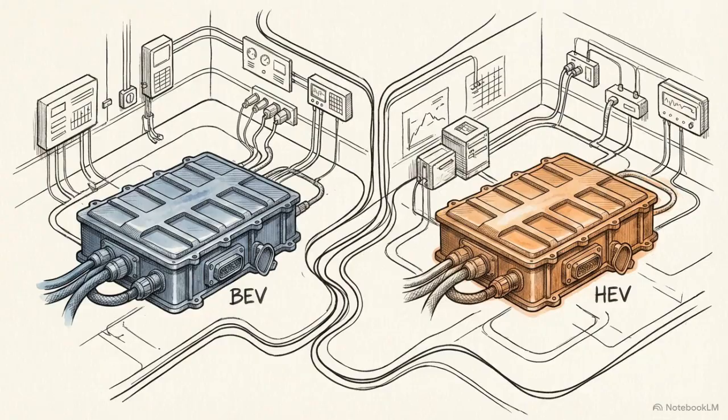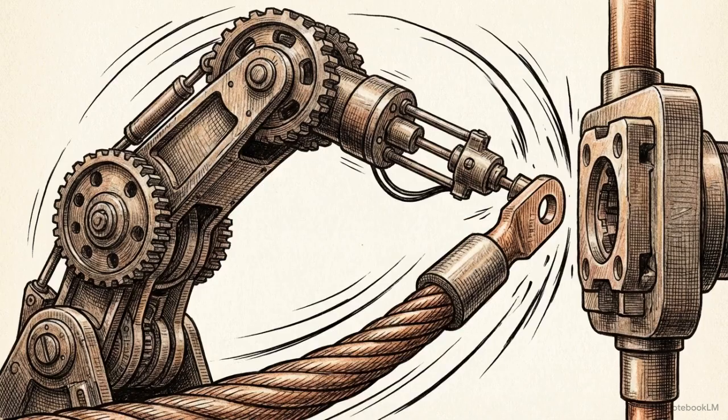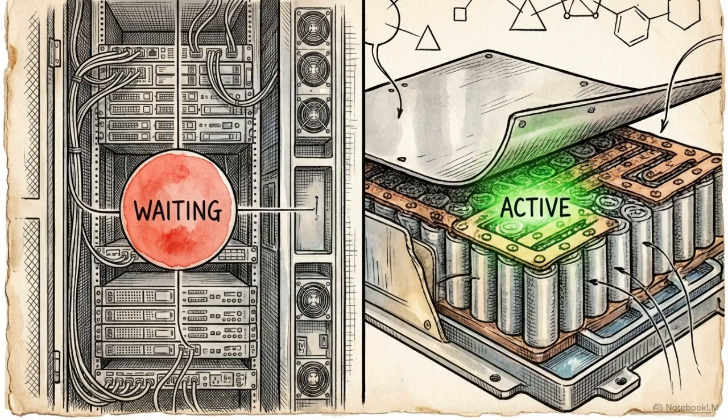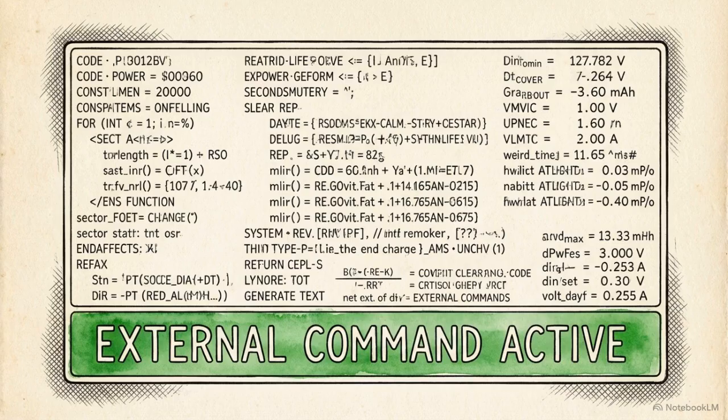This is a rigid categorization phase. A battery system cannot exist outside these two classifications. This single mathematical calculation dictates the severity and length of all subsequent electrical preconditioning steps on the test bench. Moving to the physical test bench, the battery pack is integrated using Class A and, if present, Class B high-voltage connections. There is a strict operational hierarchy here. The test bench equipment does not override the battery. Instead, it must follow the operational limits communicated directly by the battery control unit via the communication bus.